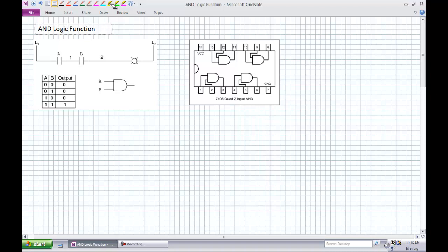For example, you want a sufficient amount of pressure, a sufficient amount of fuel, and the engine within a certain operating temperature range. You can have a number of different permissives in that safety chain. We're going to do a whole lecture on digital logic as it applies to motor controls and PLCs. Here's our line 1, our hot, and line 2, ground. So for conditions A, B, and C: is there enough pressure? Yes, there is. It closes. Is the engine within operating temperatures? Yes, it is. Is there enough fuel?